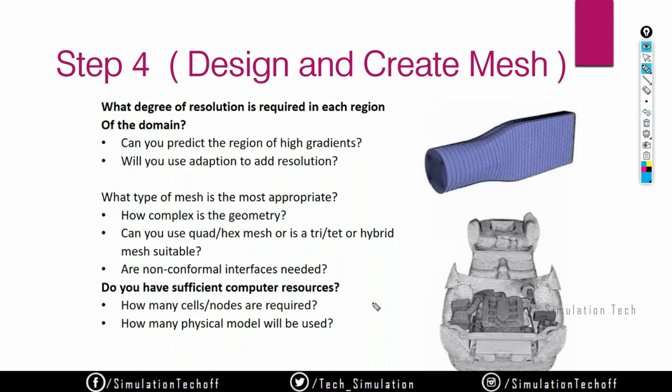If you are using a student version, you will be limited in node and element counts. For Workbench itself, you have a node limit of 32k nodes. Beyond that limit, the problem will not get solved. And for CFD analysis, you have a limitation of 52k nodes. So when you try to mesh more than 52k nodes, the problem will not get initiated. That is the drawback of the student version. If you are using a cracked version, that is not an issue.